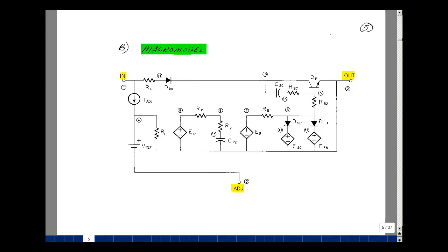This is needed because as the transistor grows in size, the value of beta F or beta DC begins to decrease. Well, in a SPICE model, I can make the beta F of this whatever I want it to be, so I didn't need two transistors, although initially I did start out with two, but realized I really didn't need it.